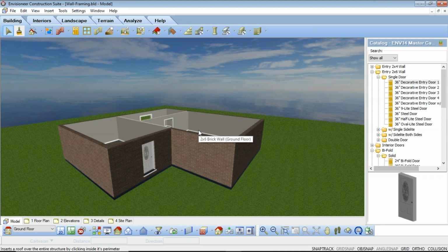Intersection framing can only be defined in framing mode, which is a specialized viewing environment that highlights and focuses on wall framing components. And that's where I was saying this lookup table is only accessible in the model itself. Because there are so many different options for it, having the model already create that intersection, once it's in there, you can now go in and modify it even further. So that brings us to our framing mode, and that's the next thing we want to look at.